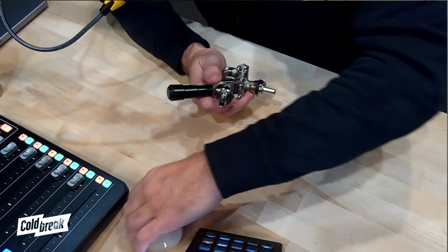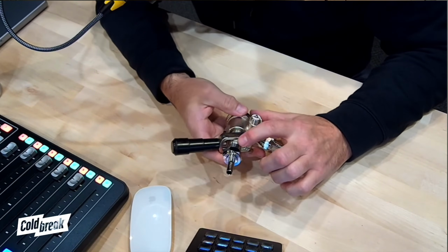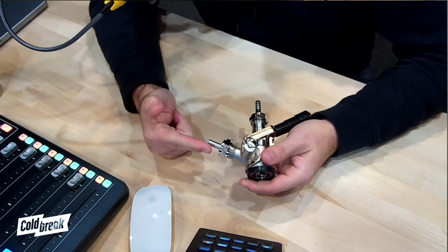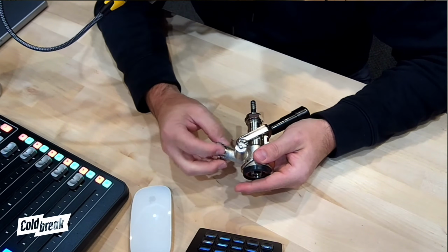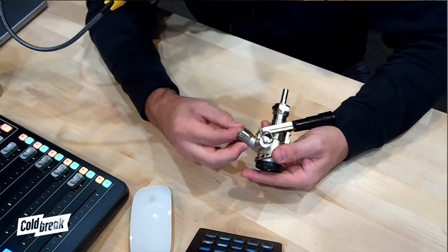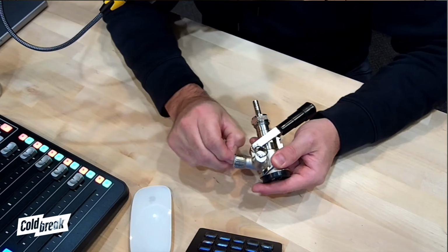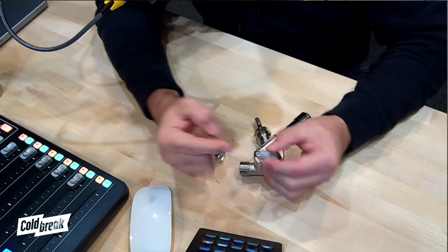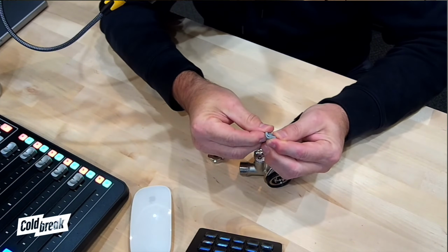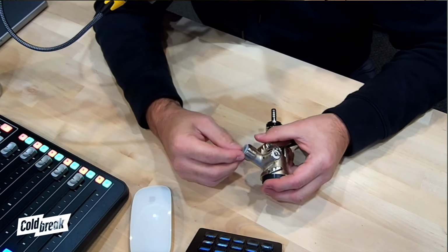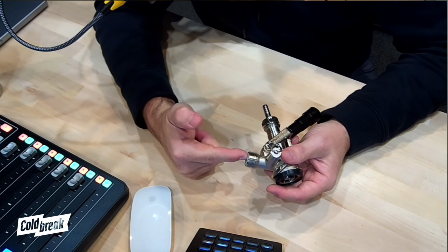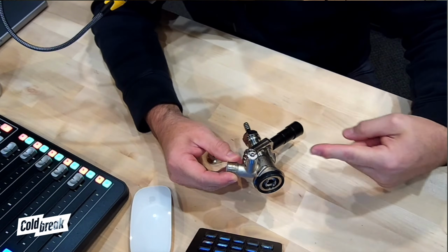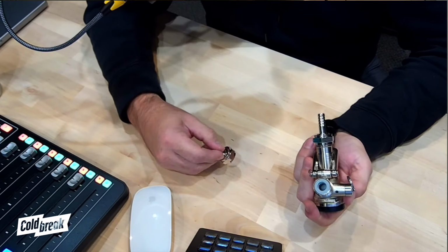All right, so I've got a beer coupler in front of me here. The top part of a beer coupler is the liquid out. The gas in is always going to come from the side. And when the gas goes in, it should enter what's called a little check valve. Inside this, you should be able to pull out a little check valve. It's like a little baffle that will open. As air enters, it opens up and allows air to go through. Then if your gas ever runs out, it prevents beer from going back up into the coupler, and it prevents beer from going into your gas lines. So that needs to be in there.